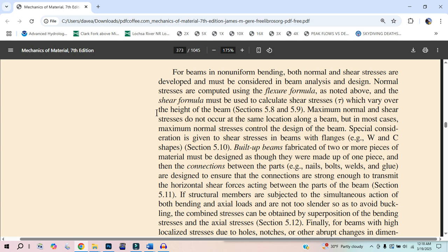Change every moment in your physics book to just a couple of forces, because if you have an applied moment, there's no magical moment fairy that comes along and puts a moment at that point. The applied moment is due to 2 forces opposing and a distance between them.